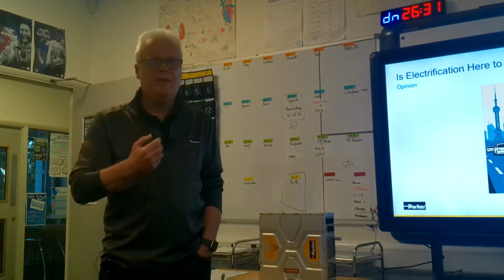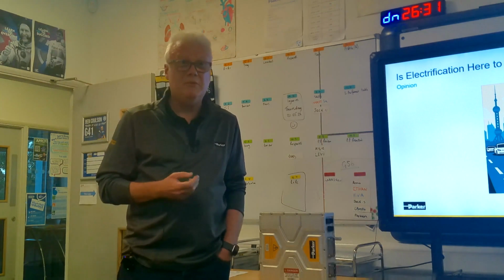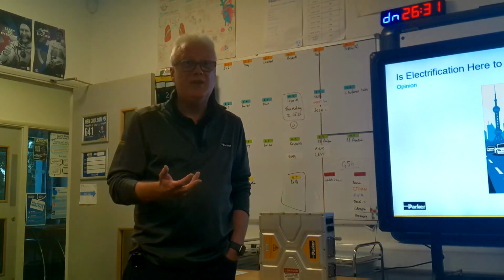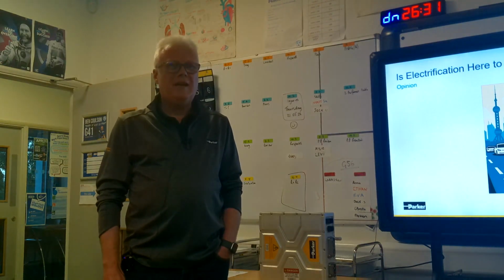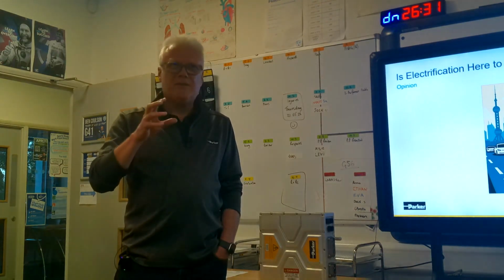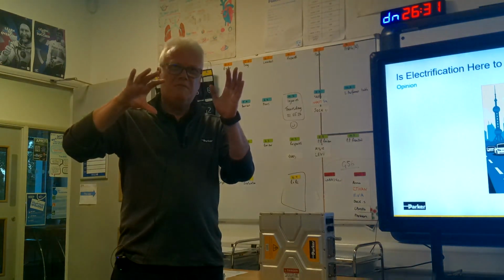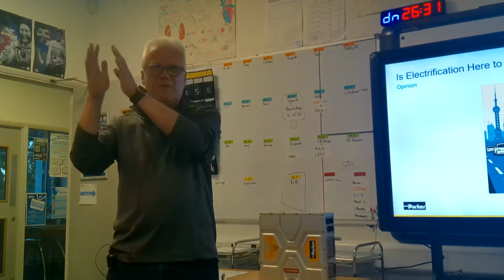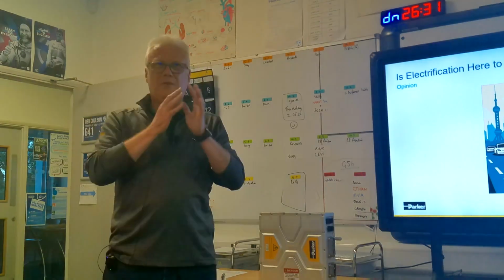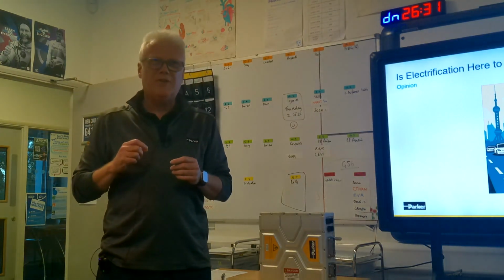Air conditioning units used to use it because it was quite a simple control system, and it's quite easy to do. There are variants where I don't use all 6 switches. I just use 4 switches and leave the third one not connected, and then just move those around. You get less volts out of it, but obviously you reduce your losses.